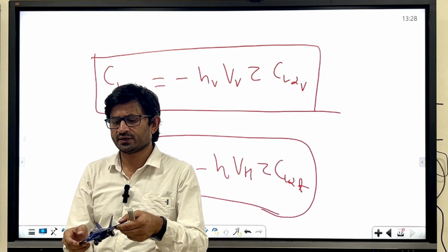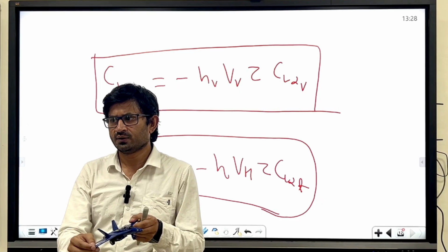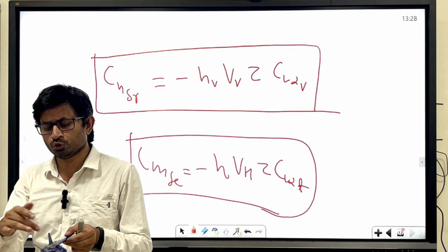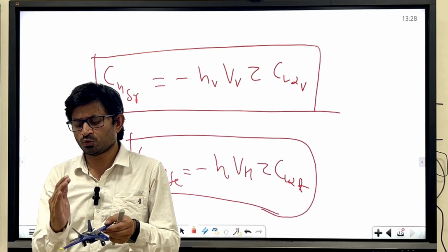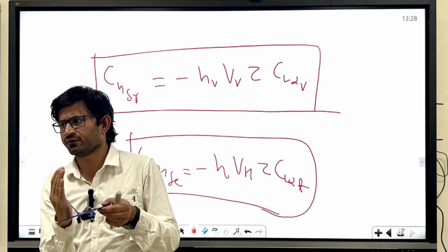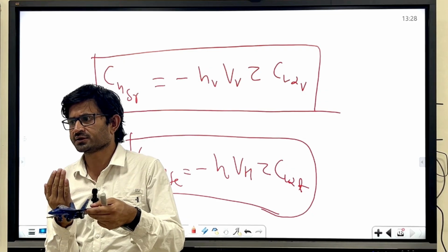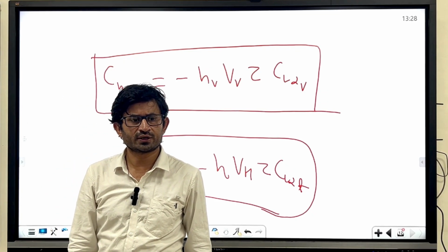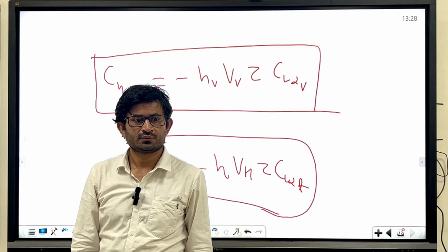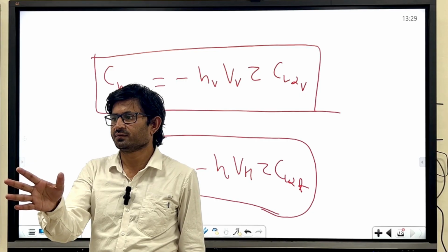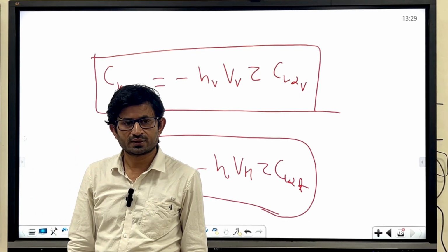That differential drag will try to yaw in this direction. But since you are rolling in this direction, you don't want this motion, right? So what will you do? You will deflect the rudder in this direction to counter this yaw. That is how you achieve a coordinated turn, rolling without side slipping. That is one job of the rudder.